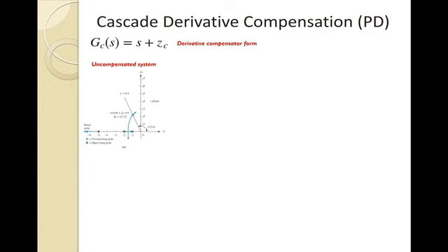Now if we look at the root locus, we can see the open loop poles right here. We have them at -1, -2, -5, and then we're going to have a gain. So for this example, our G of S will just be our gain K, which we will vary via our root locus to find a suitable closed loop system.